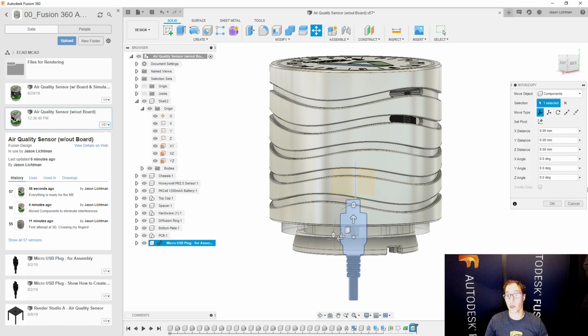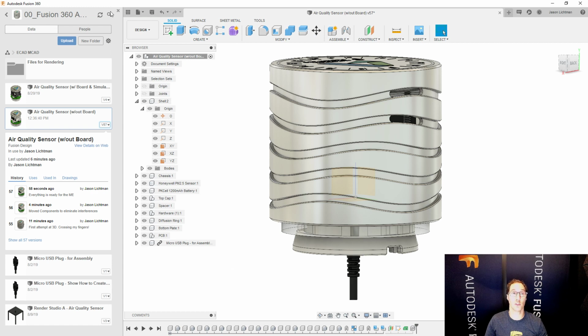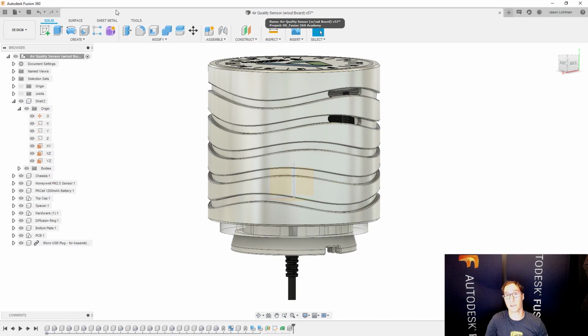If you don't want to delete that and bring it in again, you could also drag it into the assembly level, and it'll just create a new feature that moves that component from the shell component into the assembly. I hope that wasn't too confusing, but you can drag components into other components and make sub-assemblies anytime you want. It's amazing. Let's undo that too.